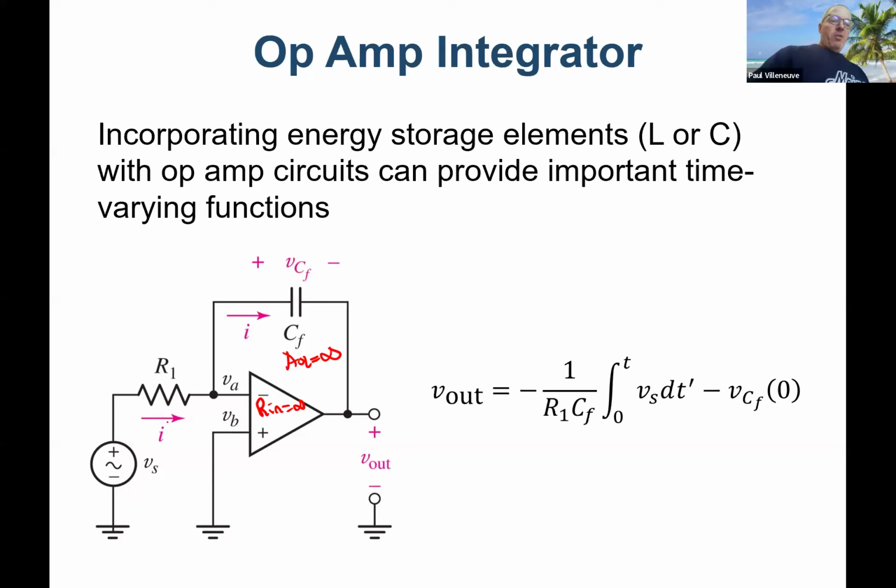And when we do that, we know that this current I has to go over there, right? First thing. And the second thing is this open loop gain is really, really big, which means that the voltage difference between these two had better be small, really small. Because if it's anything big, your op amp's going to saturate, you won't get good results. So we say the plus to minus voltage drop across here is 0 in an ideal op amp.